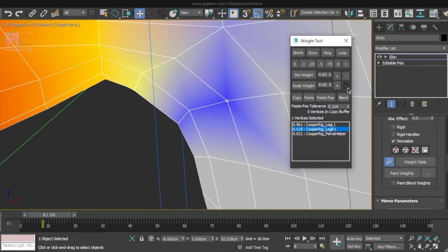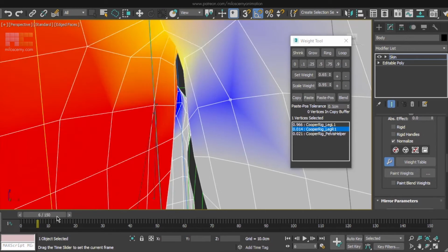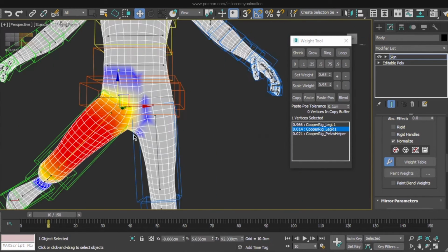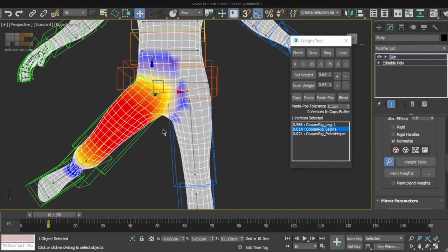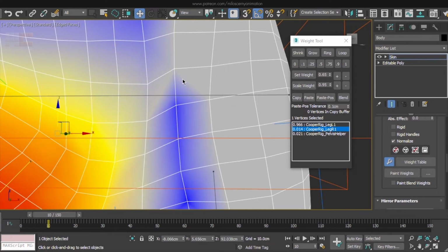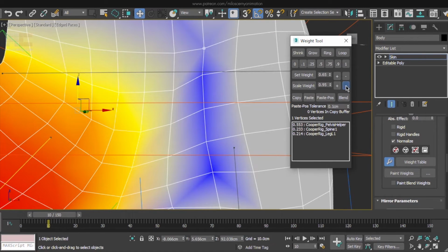You can see that we deal more or less with every single vertex. That's why you always want to skin the lowest low poly model you have. Never apply turbo smooth or any other smoothing which adds polygons. That would be crazy. Let's check out some more details we can find and improve here. This.